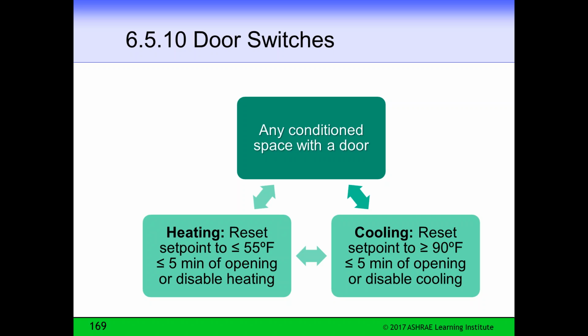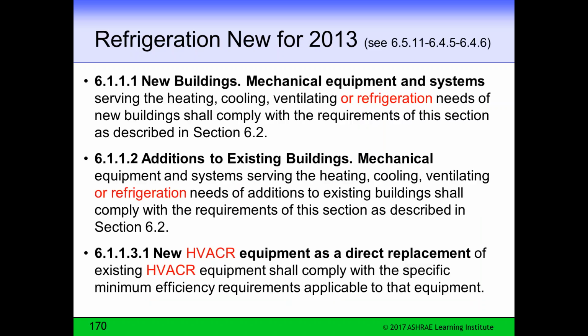The big thing is that you put a closer on that door, and you don't have to do this. So make sure that you get closers on all those outside doors, because this is kind of an expensive solution to a little problem, in that we're going to put a sensor on every door and send it back to the controls and reset our unit and everything. So you're better off avoiding that.